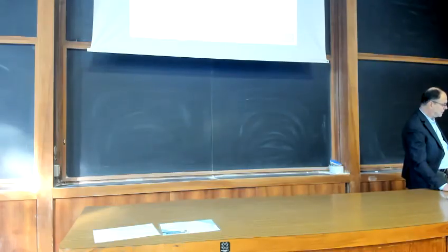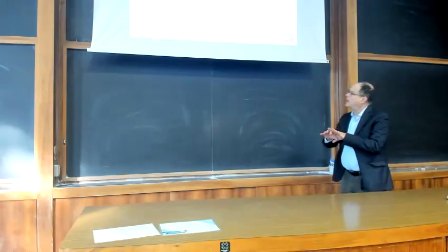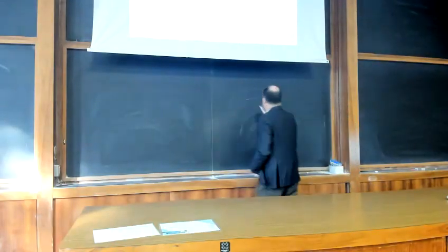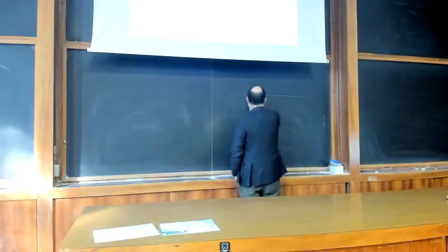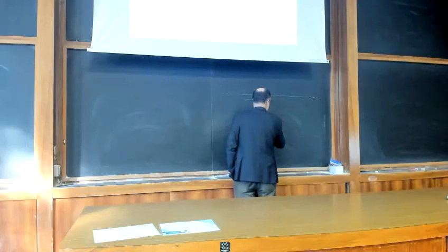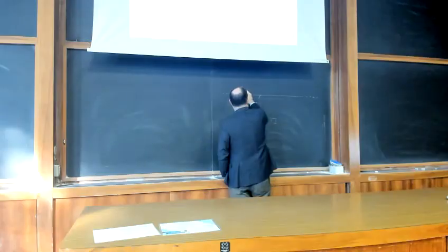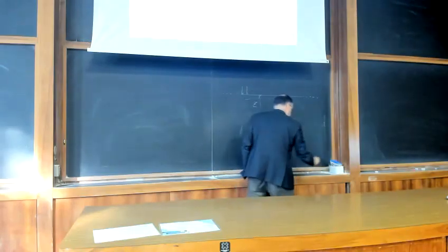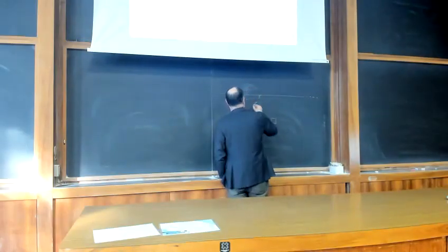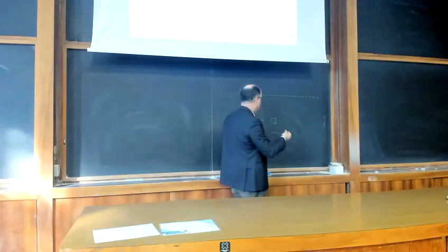Now, let's start from a very simple situation, with enough space, like the one you have already considered, a sort of one-dimensional condition, where you want to define the stress at a depth z from your ground surface. Let's assume that this is your ground surface, and you have a soil element at depth z.